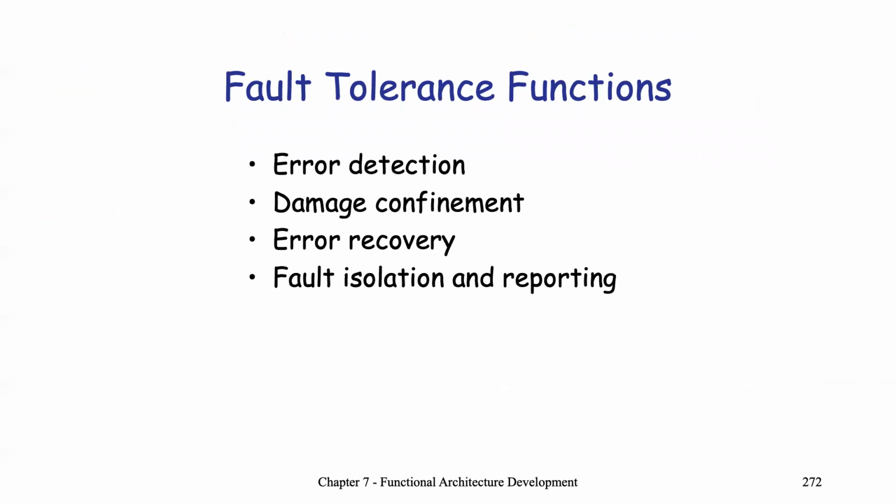So what are fault tolerance functions? And here we're talking about four. First of all, you need to do an error detection before you can do anything about that. Once you do an error detection, you can do a damage confinement, so you don't want to continue to propagate and cause more damage. That would be a great thing you would want to include in a fault tolerance functionality.